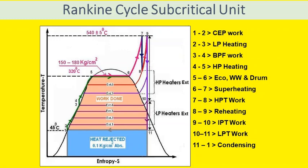From 6 to 7 it represents superheating, and this superheating, as I already mentioned, is taking place in 3 stages. And after superheating there is expansion in the HP turbine. 7 to 8 represents expansion in the HP turbine.